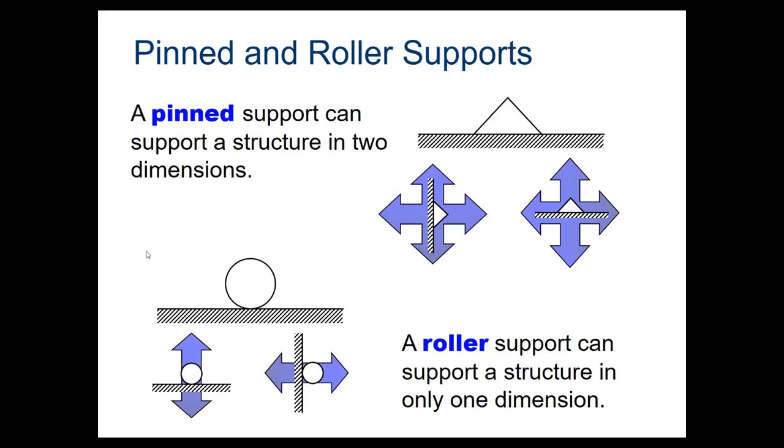The second type of joint we get is a roller joint, and the roller joint is really important in pretty much all bridges, especially with truss bridges. You don't see this the same way in concrete bridges. Concrete bridges have a different mechanism for this. They have an expansion joint where it kind of almost looks like a metal zipper thing across the roadway. So you might see something like that.